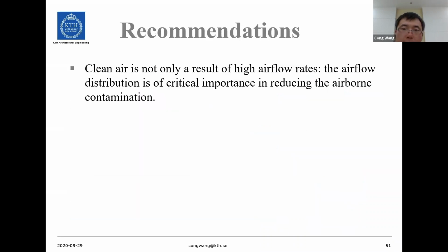So based on our research, I think we can give some recommendations for the usage and design of operating room ventilation systems. First of all, clean air is not only a result of high airflow rates. The airflow distribution is of critical importance in reducing the airborne contamination.